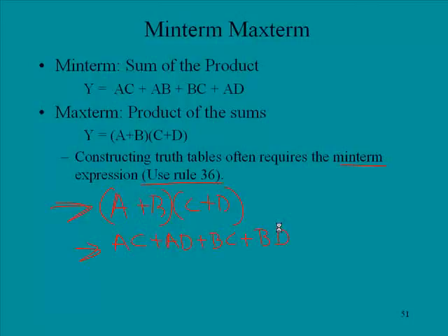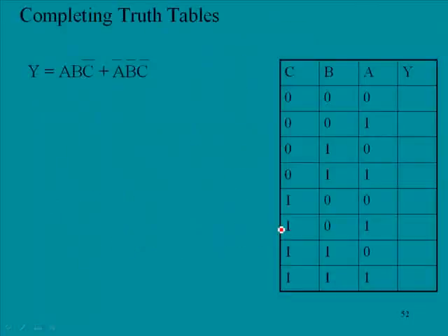And so we have a couple of truth tables here. Here we have a three-variable truth table, and with three variables, if you take 2 to the third, there are 8 possibilities. We start out with 0, 0, 0, and we count up to 1, 1, 1, which would be 7, and so that makes our 8 combinations. So we would get a high when these conditions are met. And so A would be 1, B would be 1, and C would be 0.